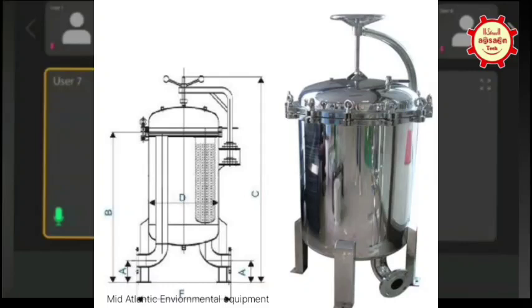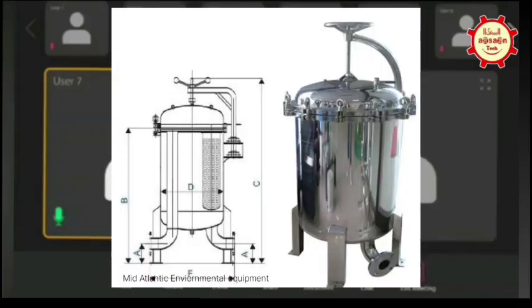Just a minute. There is one question I have regarding a tube sheet kind of attachment for a non-heat exchanger vessel. Let's say a vertical vessel with a tube sheet, or a filter plate, as some might call it. How do you verify its thickness? What is the material of the tube sheet? Material is CS. It is being designed for a differential pressure of 3 bar, and the tube sheet is inserted inside the ID of a 2-meter vessel and fillet welded to the vessel.